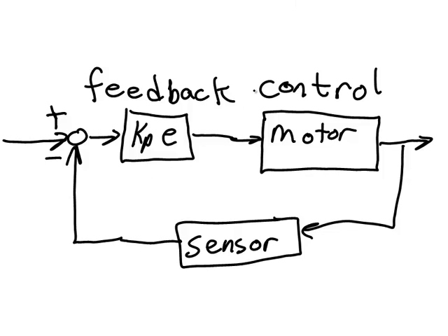I want you to notice what the input and the output of this controller are. The output of the controller is the input to the motor. That means that the units on the output is voltage. Now, what are the units on the input? The input here is the error. This is error in positioning because we're doing position control.